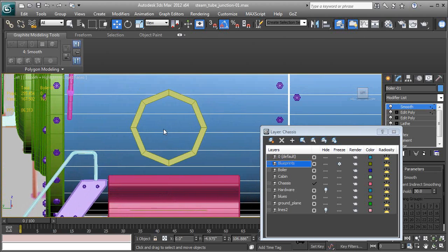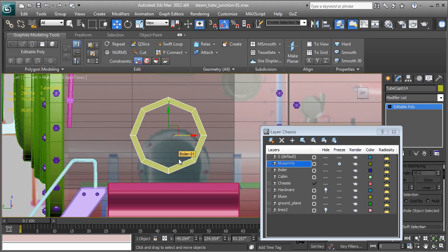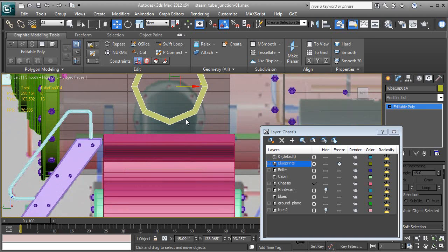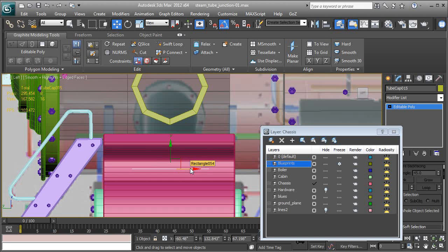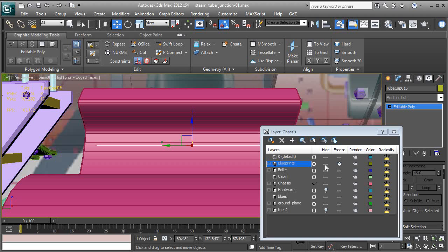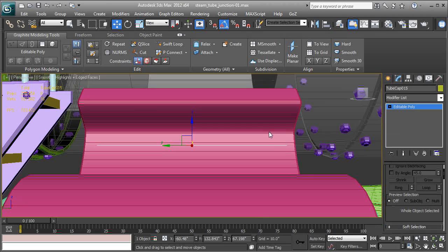And left view, L. Let's click on the boiler and Alt and X and see if this circle is roughly the size of that. And it is. It did a pretty good job by eye. I'll center it up a little bit more, and grab the other one. There it is. Center that up just like that. Perspective. We can hide the blueprints again. They're not explicit reference. We're just using them as a guide. Hide the layer manager. Perspective.